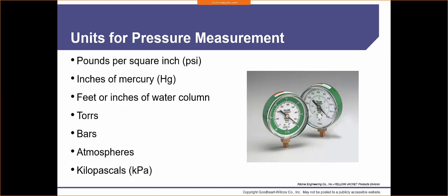Our household water pressure is about 50 psi. That's a lot. Everybody's, I'm sure, seen the water hose flowing, and you know what 50 psi really feels like. Imagine if that were gas. That would just be utterly insane. There's so much heat energy associated with gas that we don't need such a high pressure. So we're talking about less than 1 psi when we're talking about gas pressure.